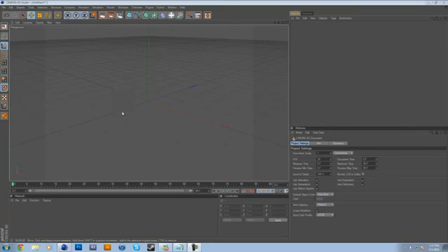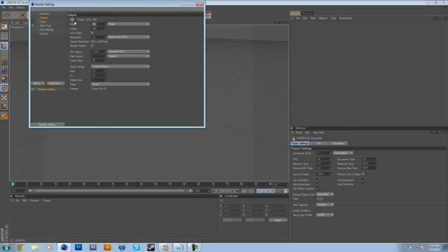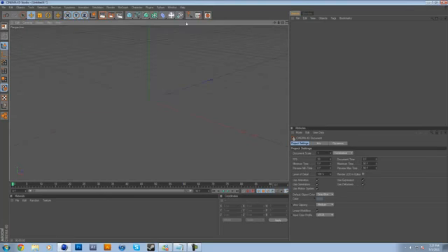There's a couple of things I'm going to do just before we start. I'm going to set my viewport aspect ratio to 16:9. The reason I do that is you can see these dark sort of bars on the edges of the viewport, and that really distracts me. So I'm just going to go to our render settings, change that to 1280 by 720. That is just completely personal preference. It may not bother you having those bars there, but it does me.